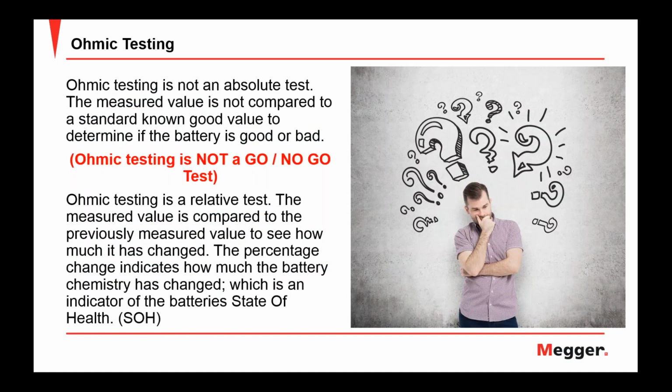Now, one of the important things to understand about ohmic testing is it's not an absolute test. This is not going to tell you this battery is good, this one's bad.